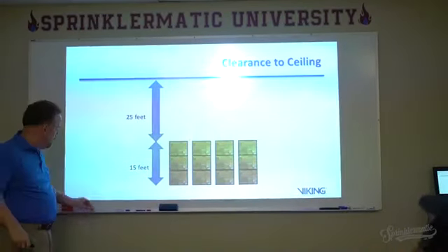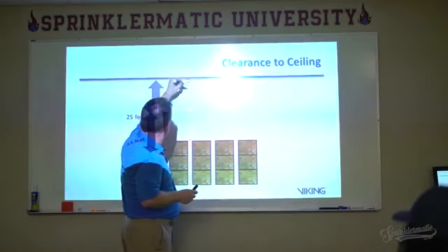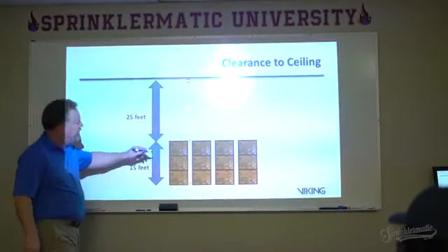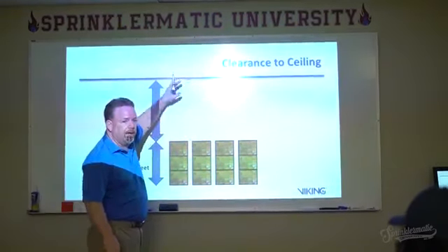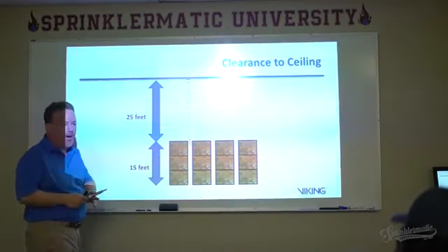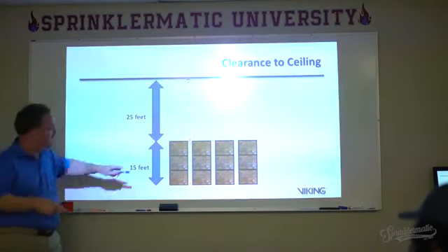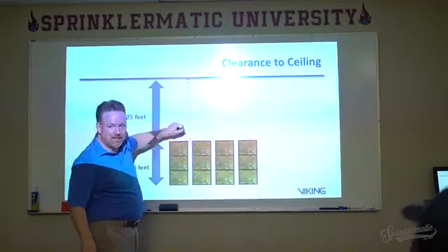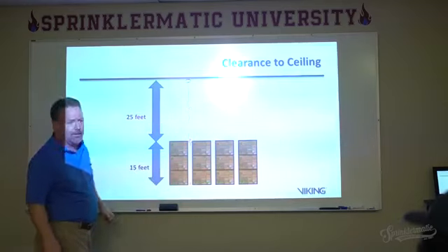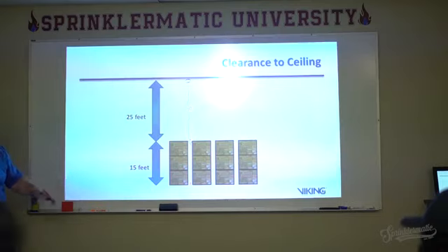The further up it goes, and I've got my sprinkler up here, the more velocity that's created, the greater this plume becomes, the more difficult it is for the water droplets to penetrate down through the plume. This becomes a big challenge, and it's not what you expect. You'd say, well, less material, easier fire to put out.